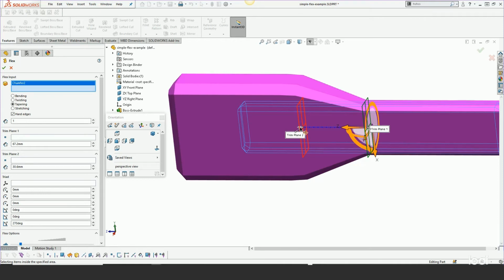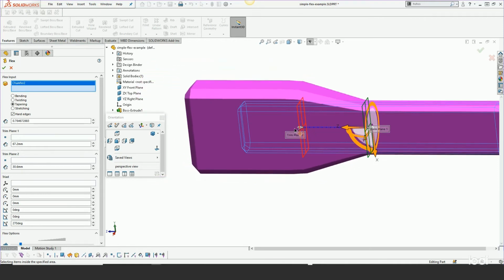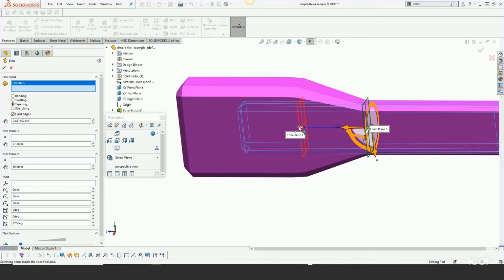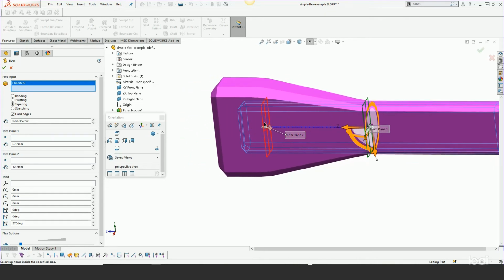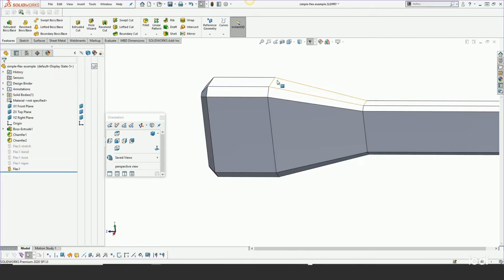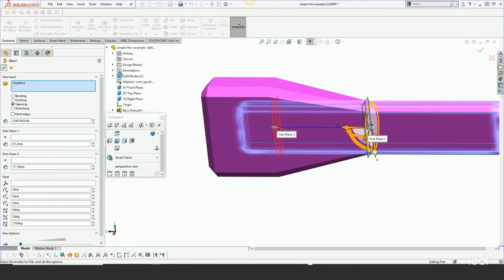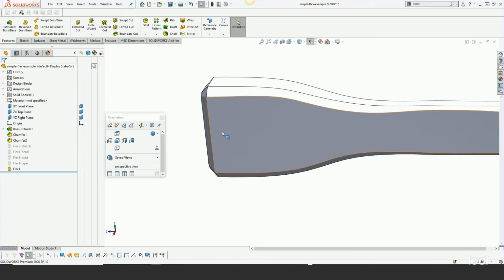Now, again, right mouse click will grow your offset value of the taper. Left mouse button will move where you want the taper to occur. And usually you want hard edges on this option, so you get hard edges between the flexed area. If you turn that off, you get something that looks like this. It tries to make it continuous. For flex, it's not especially good. It could be good for some of the other flex types.